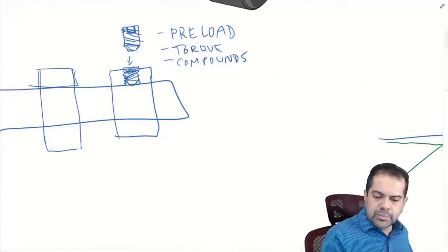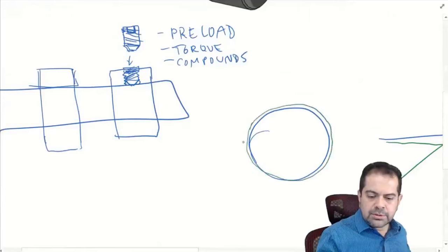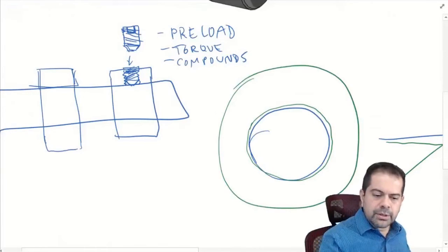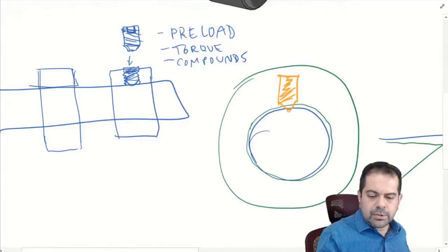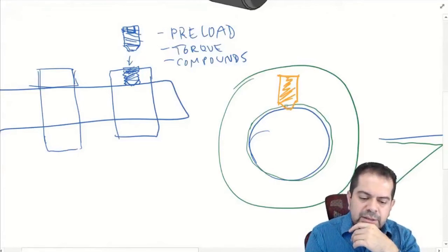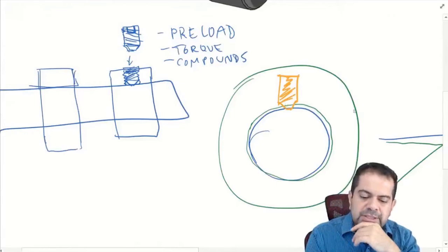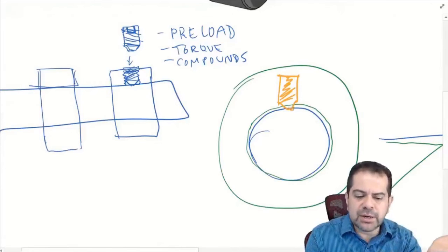I'm going to draw it a little bit bigger than that. You have the shaft. Let's say the color is green. Something like that. And the color, you've got the set screw. Okay, another issue is if we think tangentially in relation to the shaft, this shaft can turn because the set screw is just on the outside,